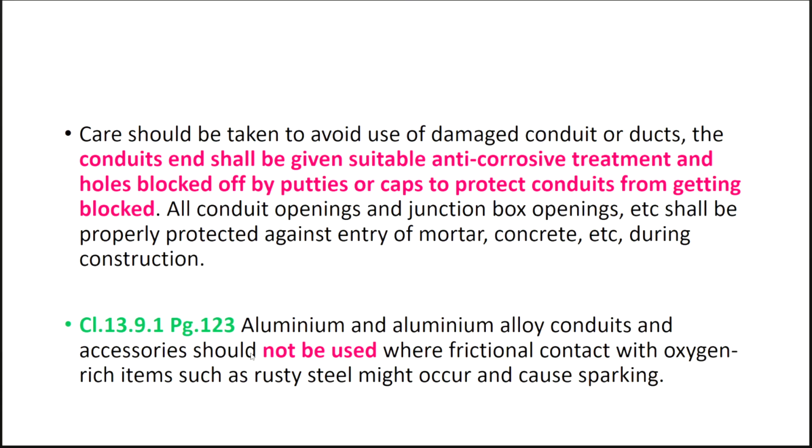Clause 13.9.1, again page 123, specifies that aluminum and aluminum alloy conduits and accessories should not be used where frictional contact with oxygen rich items such as rusty steel might occur and cause sparking. So you should avoid aluminum related conduits.